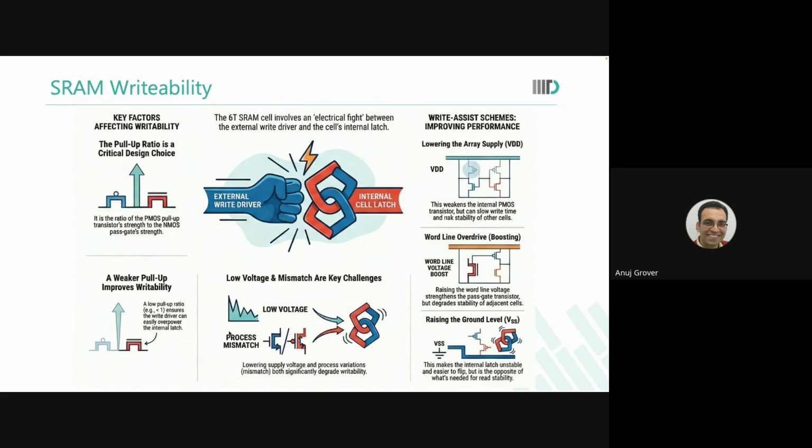Ground, we did the layout of the SRAM cell first. Why? Because now you know that the same via that gives you ground is shared across 4 cells. See, the way we are flowing through the class, there is a reason behind it. I could do the layout even now, no? I could have talked about these things. But then you would not be able to appreciate that even if I touch each ground rail separately, as soon as I say raise the ground, 4 cells come at risk. I want to write only into 1.